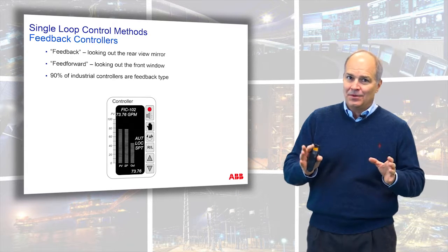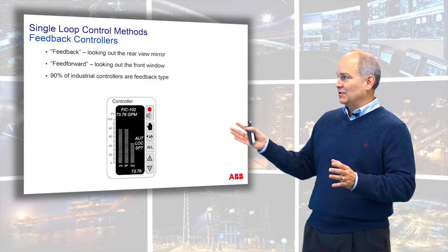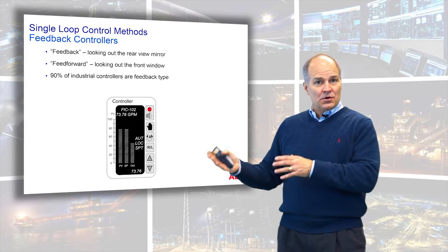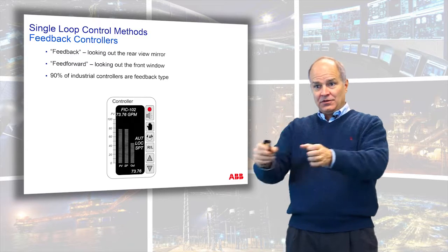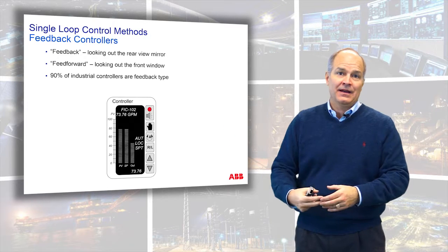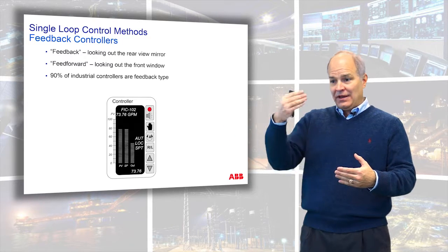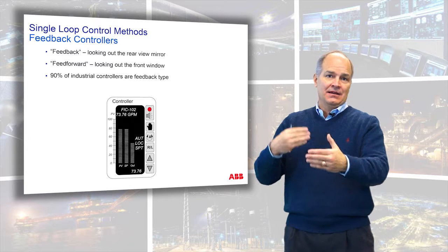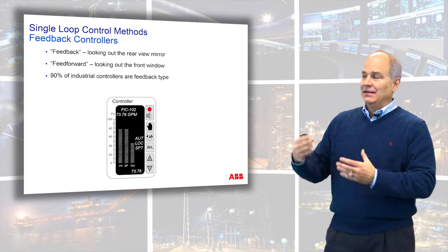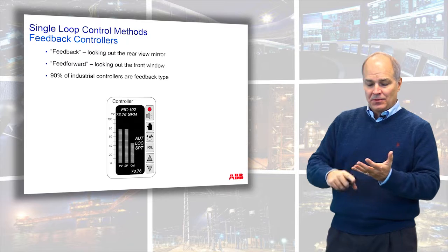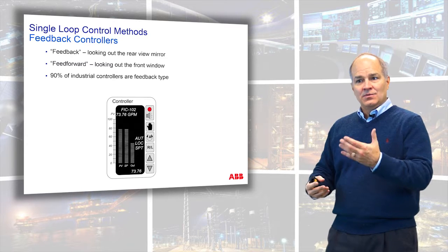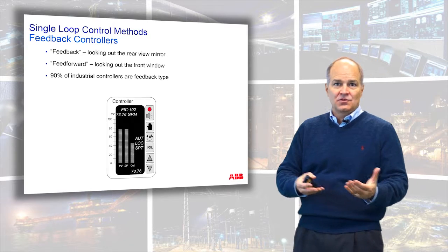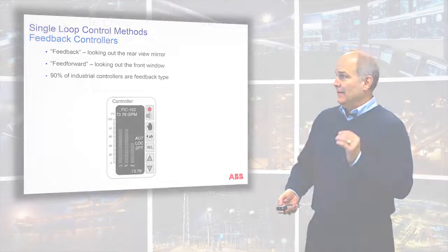That's kind of an important distinction on controllers, as opposed to feed forward. Feed forward is like you're looking out the road and you see a pothole and you adjust for it before the error happens. Feedback control, you had to hit the pothole and then you're always late. So keep in mind that feedback controllers, proportional, integral, and derivative, are reactive in nature, and that is what defines the control actions and the way you tune them.